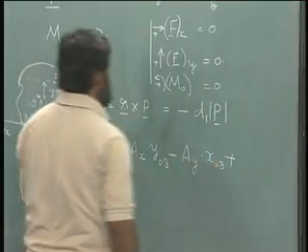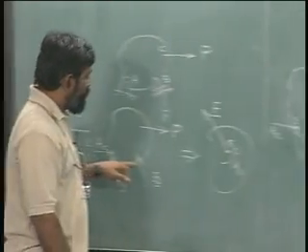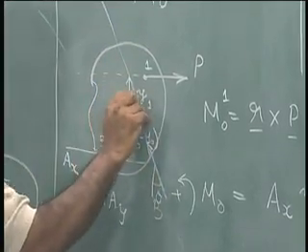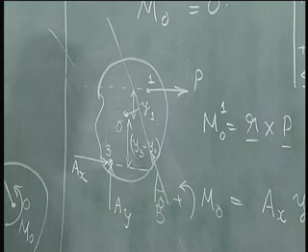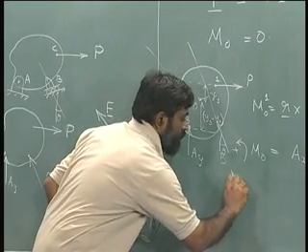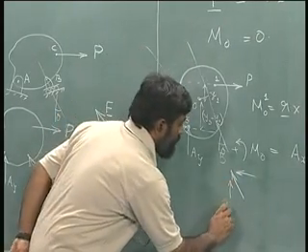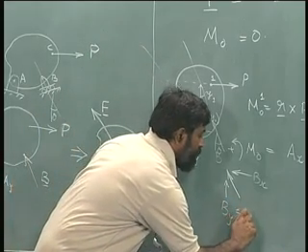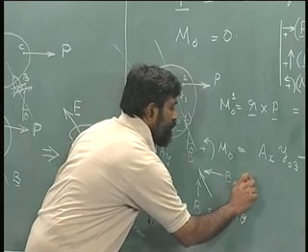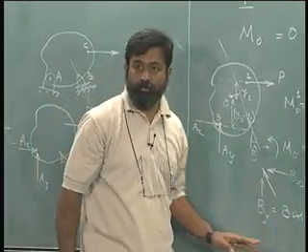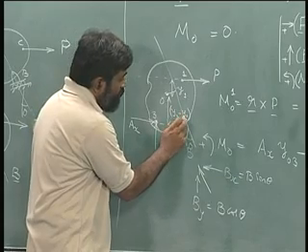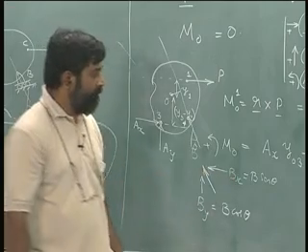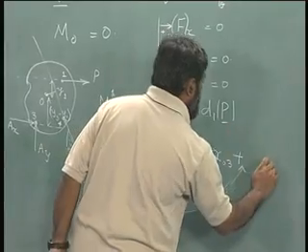Okay. Let us complete this by adding these. There is this force B that is acting, let us say that is acting like this, at an angle theta. Again I can find out the perpendicular distance from it and use that. Alternatively, I can also write this force as two components like this. This is By and this is Bx. In this particular case, given B, I can write By equal to B cos theta and Bx equal to B sin theta, where theta is already known. Okay. By writing this, if I take this coordinate, let us say this is 4, I can use the coordinate and write the moment with respect to By separately and Bx separately. Okay. So, I will add that particular part to it.